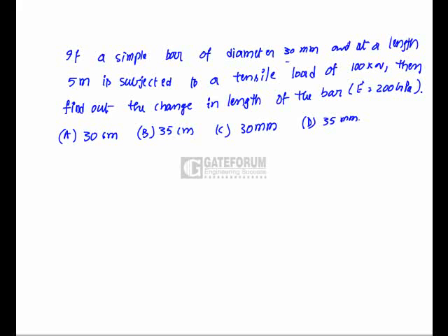A simple bar of diameter 30 mm and a length of 5 meters is subjected to a tensile load of 100 kilonewtons. Then find out the change in length of the bar. The E value is given. So here we have to find out the change in length.